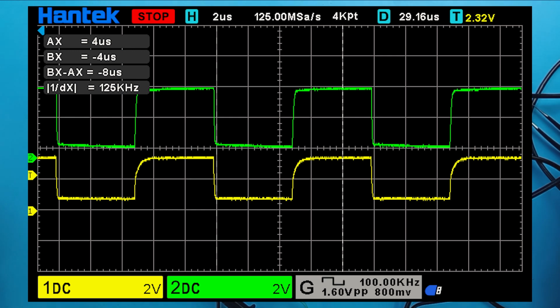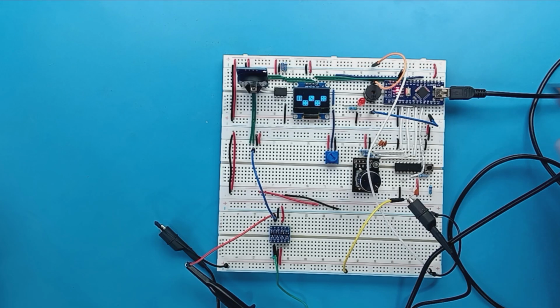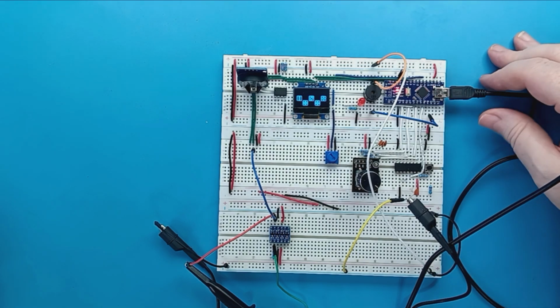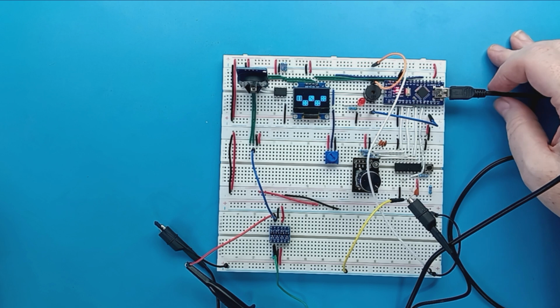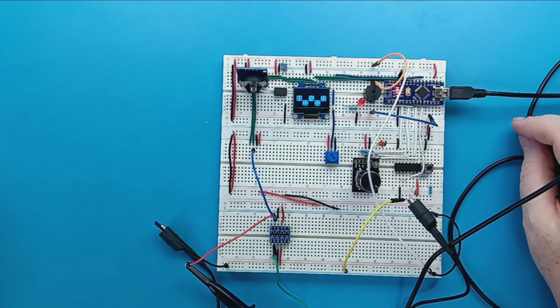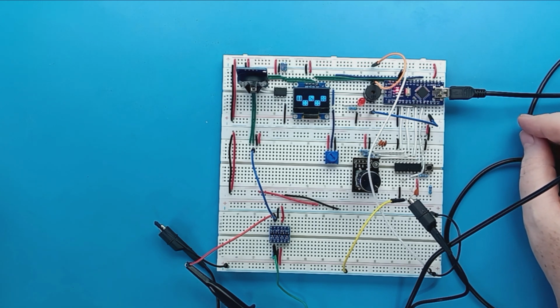The reason it's a little low is actually the amount of power coming through the Arduino Nano is a little bit limited. As I say, I've got a few other little things, but it's not really regulating the 5 volts. It's taking the 5 volts from one of my hubs, and that isn't actually outputting a really good 5 volt level.